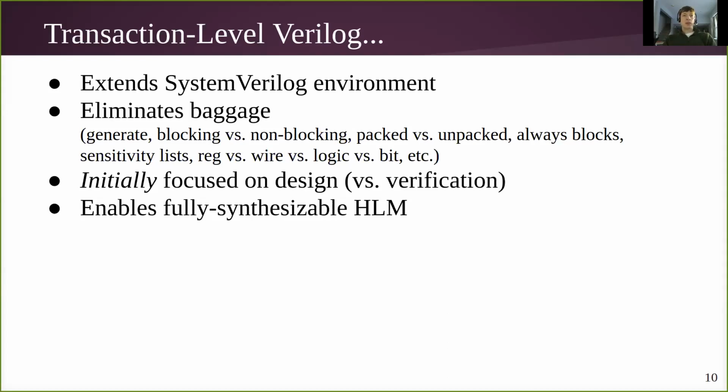And there's also a very strong benefit from modeling HLMs in a way that's synthesizable. So obviously everything in transaction level Verilog is synthesizable constructs. It's not only a good language for doing high-level modeling, but it's one that's fully synthesizable. And that means you can target your verification modeling to hardware acceleration on hardware emulators.